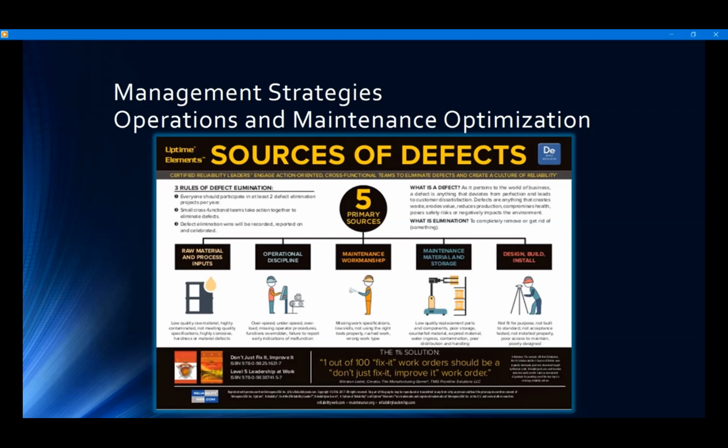A traditional maintenance-focused technical approach to reliability will focus on the first three sources through preventive maintenance, predictive technologies, vendor audits, parts inspections, and skill training, but will typically ignore the last two sources. When you focus on limiting all the sources of defects as well as eliminating the defects currently in your system, performance improvement will be dramatic.